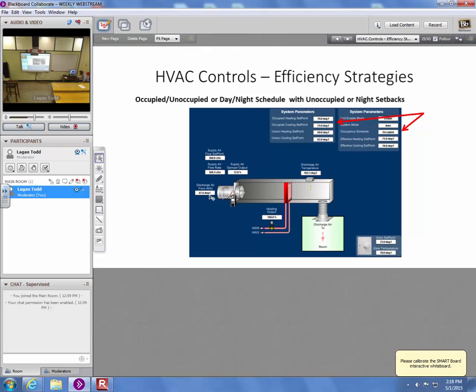It's telling us the temperature of the air coming in from the air handler at 67.5 degrees. It's telling us the heating valve is wide open, at 100% command. It's telling us the discharge air temperature right now is 103.3 degrees, so it's clearly heating, right? So why is it heating? We can see the zone set point is 72 and the zone temp is 70. So it's 2 degrees under set point, so let's try to bring it back up.